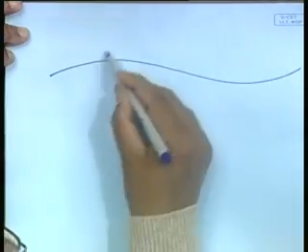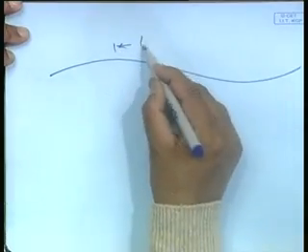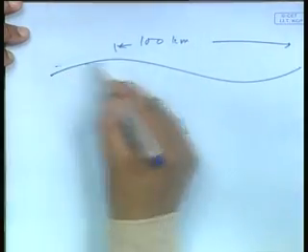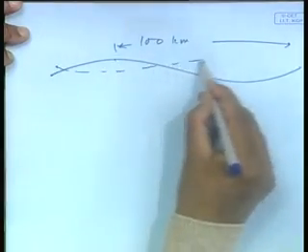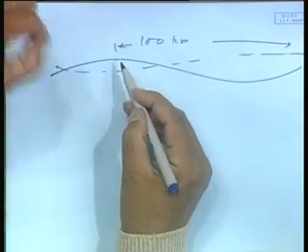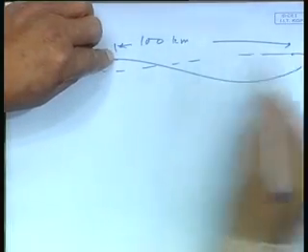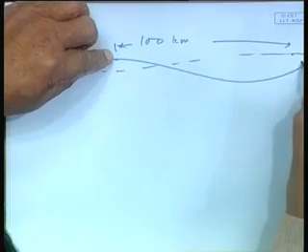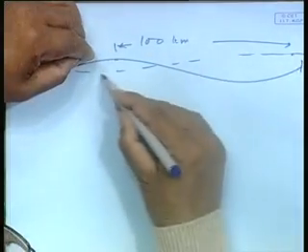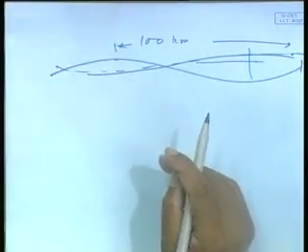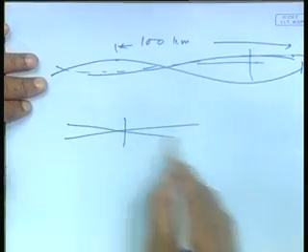The reason is very simple. If the wave is very long like that, let us say this is actually say 100 kilometer, what happened after 20 minutes, this water has come down here and this has moved up here. So the form appeared to have moved from here to here in 20 minutes. So after 20 minutes this place would appear to be having a trough. So it is like an oscillation. This oscillation was like this at one time, next instant it becomes like that.